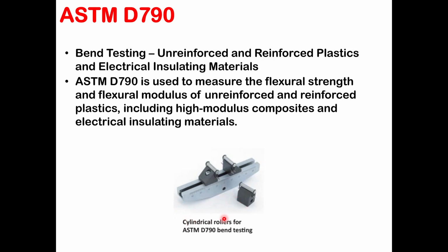Roller for this specific type of bending test. These standards include detailed specification on the recommended bend fixture for this type of testing as listed here. The rectangular specimen is loaded by a loading nose midway between the supports, which essentially means that we have a 3-point bending or 3-point loading, which you have already seen in the lab.